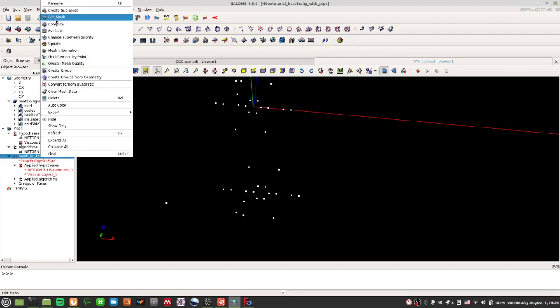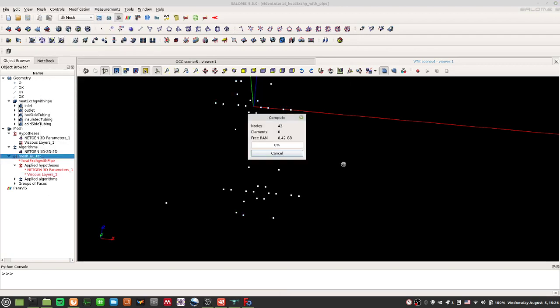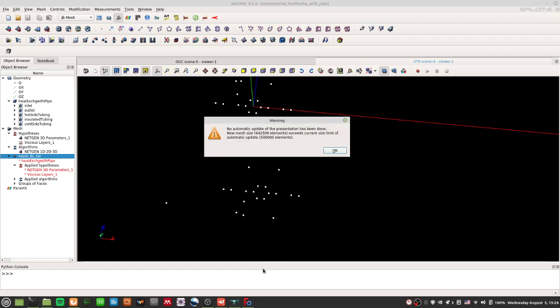I'm trying to get the boundary layer thicker so that I don't run into the problem of having too thin a boundary layer later on, because what polydual mesh tends to do is take the boundary layers and make the thinnest layer even thinner because of the way the dual mesh is created.